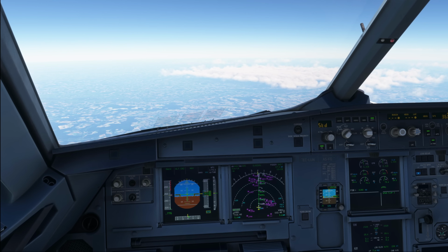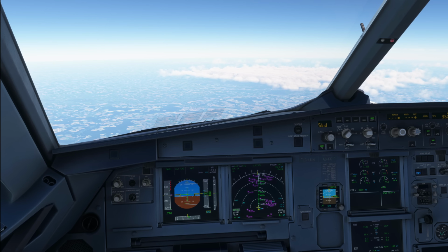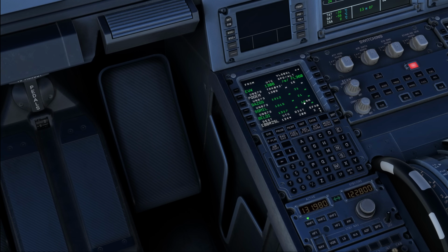For the cruise, remember the optimum flight level increases as aircraft weight decreases, so the flight crew should monitor their optimum flight level and do step climbs at the most appropriate points. Now, most appropriate points for step climb, if you look into the flight plan page and you go on to the step outs, you can either define a step climb by entering the altitude and the waypoint from the flight plan, but you can also just go for it like this.